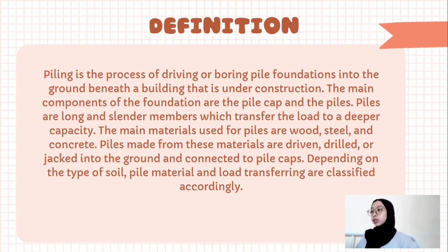What is piling works? Piling is the process of driving or boring pile foundation into the ground beneath a building that is under construction. The main components of the foundation are the pile caps and the piles. Piles are long and slender members which transfer the load to a deeper capacity. The main materials used for the piles are wood, steel, and concrete. Piles made from these materials are driven, drilled or jacked into the ground and connected to the pile caps. Depending on the type of soil, pile material and load transferring, they are classified accordingly.